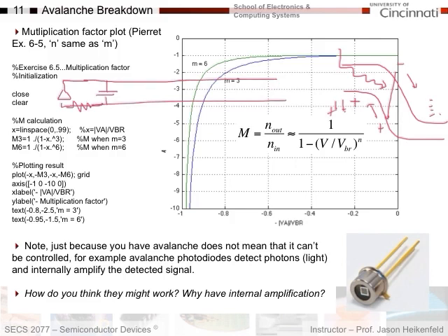One of the advantages of putting the amplifier inside the diode is that if I have a long line or parasitic capacitance that goes later to my amplifier, shown here, instead of trying to get the signal down this long line where I have RC time constant issues, if I amplify locally, I will be able to charge this line much more strongly and get the signal out of my circuit. So avalanche photodiodes will help to detect really weak signals, or give you higher frequency operation than you could achieve with a regular photodiode, given all the parasitic resistance and capacitance.